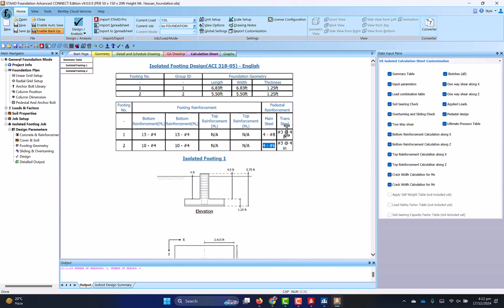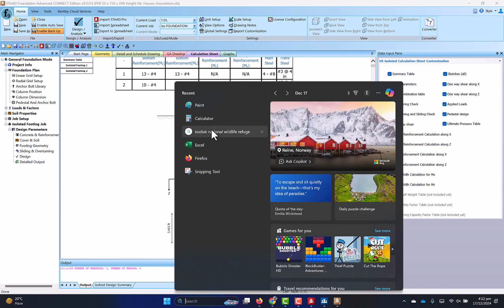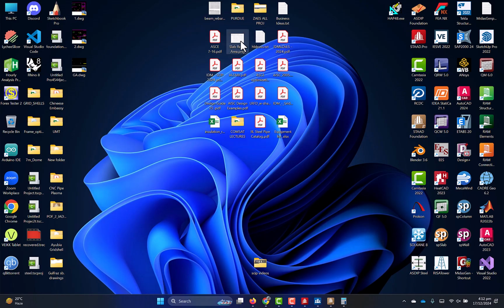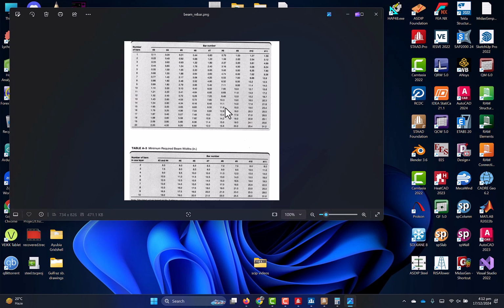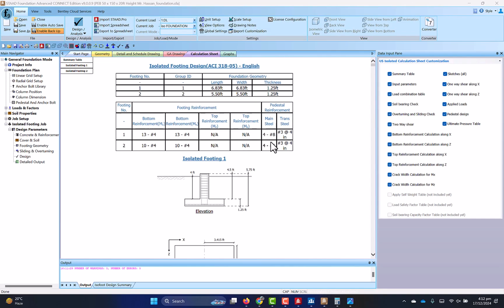at least we need to enforce minimum steel here for the pedestal. So you have 1 feet by 1.5 feet, Abdullah. So what should be the minimum steel here? 12 into 15 inches multiplied by 0.01, which is 1%. So 1.8. Now 1.8 is the rebar area. If number 6 bars are to be taken, 1.8 is almost 4 number 6 bars. So 4 number 6 bars should do the job. 1.76. So this is okay. So this is okay steel.